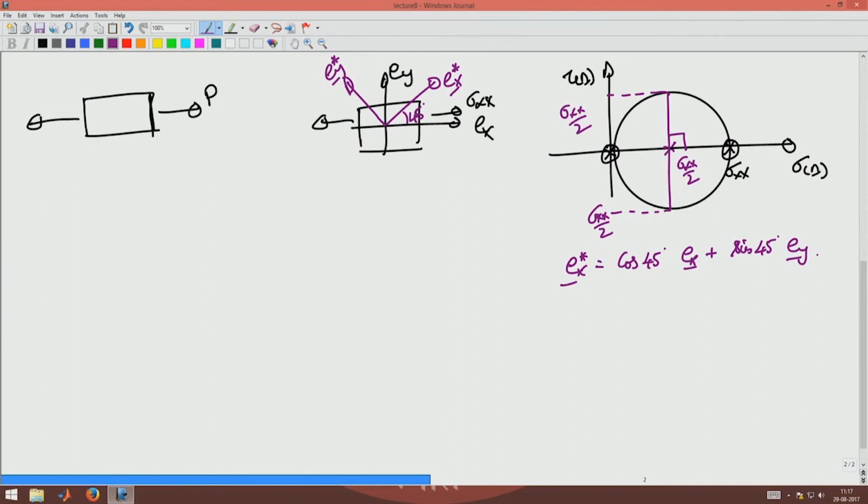Okay. Now, let us not go by your Mohr's circle or transformation rules, but just let us do it by area transformation and components of forces, how you get the same expression for the stress at 45 degree plane. That is, if I cut this at 45 degrees, what is the stress on that plane is the question that we are going to answer now. So, basically you have this 45 degree plane whose normal is n, which makes an angle 45 with the horizontal.